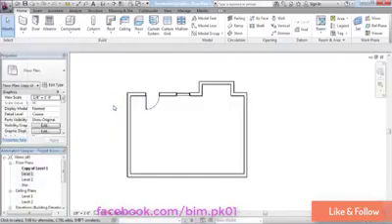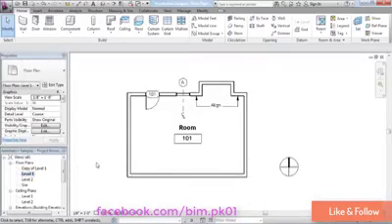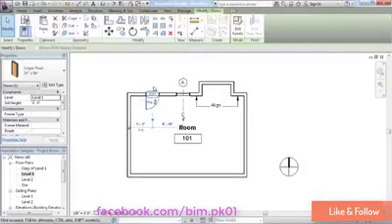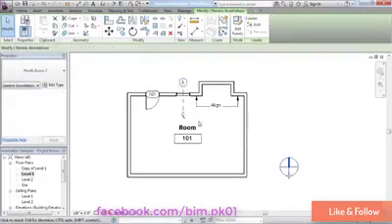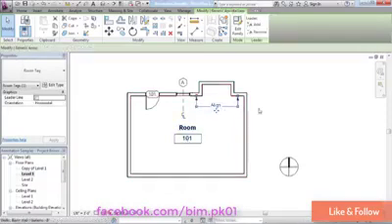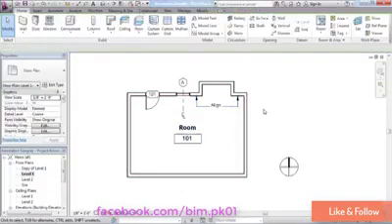So I'm going to choose Duplicate, and what you're going to see is the only items that are left behind are the items that are actually model elements. So all the stuff that disappeared, that was the annotation. And all of those are families in one way or another. They're just different kinds of families. This and this is a tag family. This and this are just generic annotation families. This is another tag family. This is also a generic annotation family. So they fall into these different classifications, if you will.